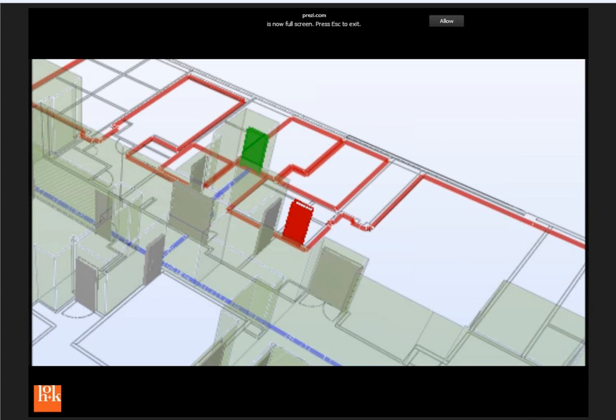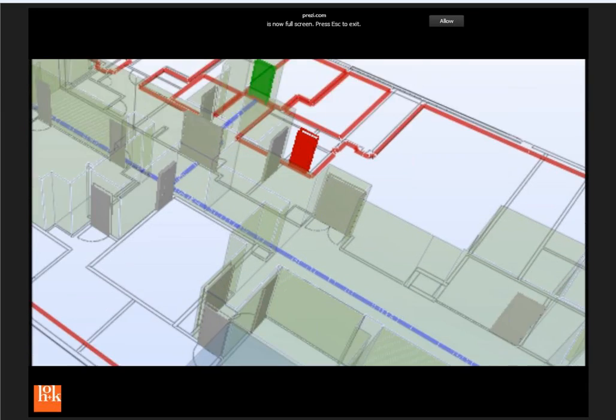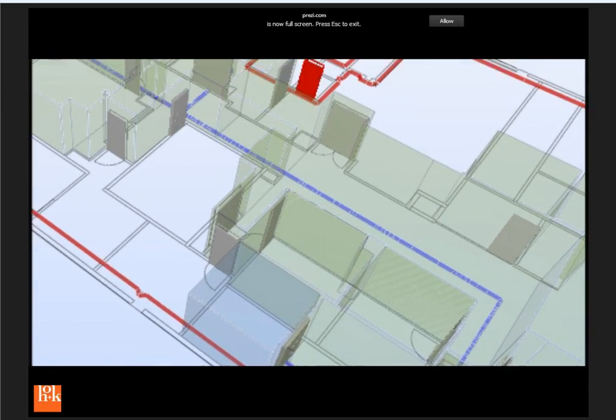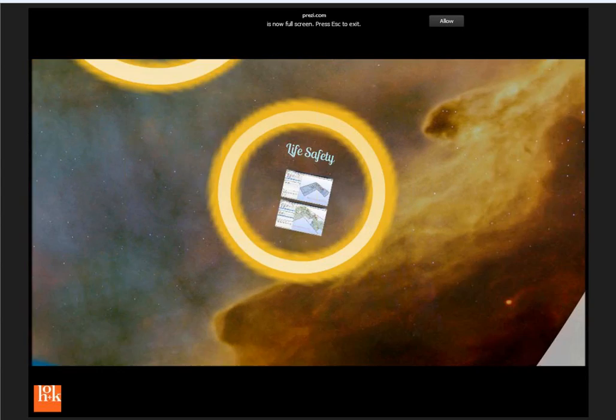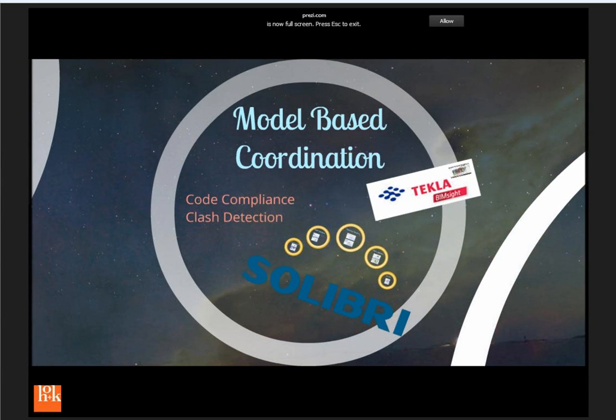So again, useful things. Yes, you can do this manually. You can use the good old Steve Stafford widget guy, right? You draw around and measure out and schedule and get the total length of egress. But to be able to do it with an IFC file inside a model checker, and report it cleanly, is quite useful.